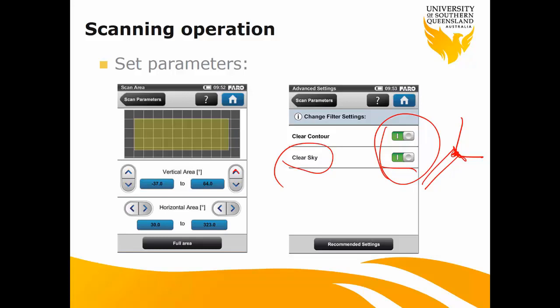That means with a very clear sky, the instrument can treat the clear sky as a mirror, so sometimes you will get some funny returning points, which we call no-object returning points. So we turn this filter on, and about 95% of this kind of no-object returning points can be removed. Different instruments include different extra filters or algorithms to ensure the scanning quality.